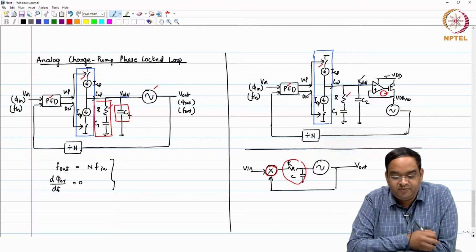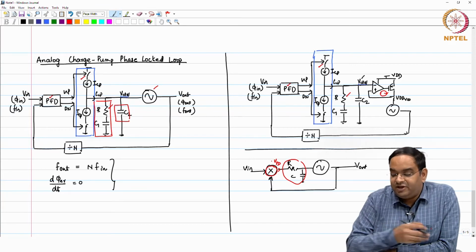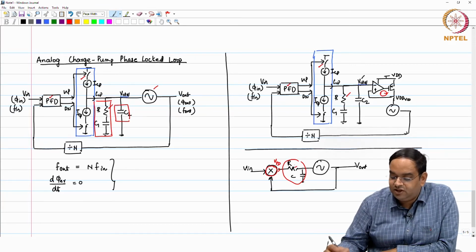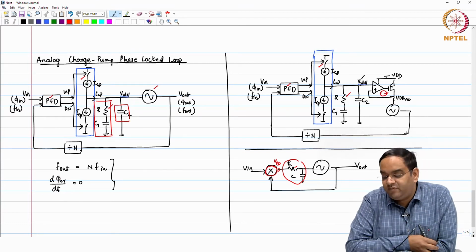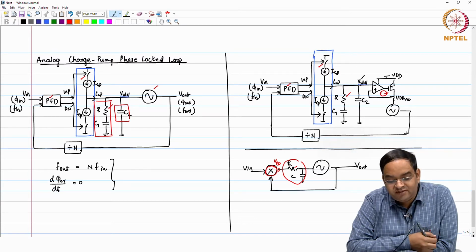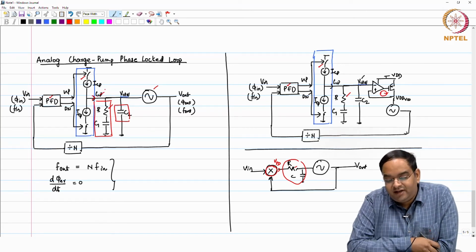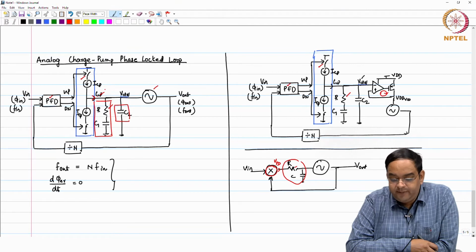Then conversion from the phase error, which here you see that this mixer output was only VPD. The average was done using the loop filter. Now, we need to convert this, because in place of using sinusoidal mixers, we are now using square wave clocks. So, we need to convert this pulse width modulated signal to our equivalent current or voltage. The current summation was easier. So, we added ICP here. So, this is how we converted, and after this we control the oscillators. So, that is how we come to know about it.